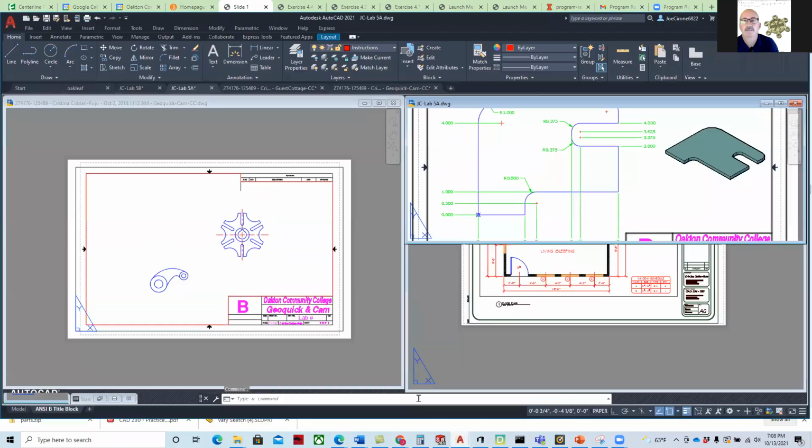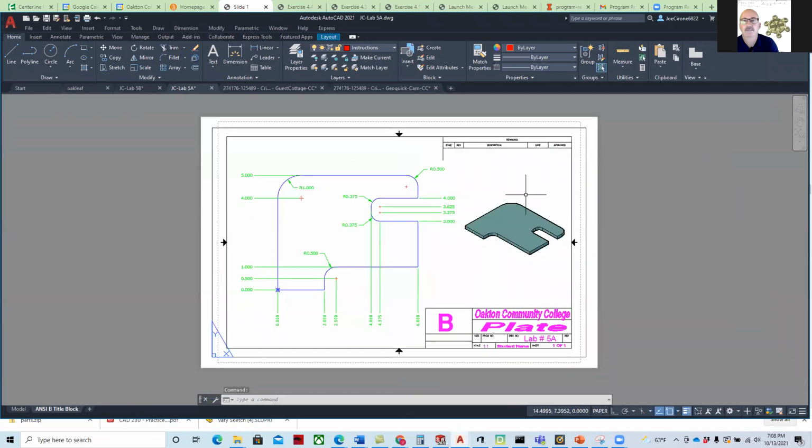So let's pull up last week's drawing right here. This is a great example where we have our origin or our XY axis at this point right here. And then the dimensions are ordinate dimensions in the X axis going this way and in the Y axis going this way. And then we can get those positions with absolute coordinates. So for example, if we wanted to locate this circular radius, we would locate that at X 2.5, Y 0.5. If you're running a CNC machine, numbers like that work really well because most of those machines are programmed off of a G90 or an absolute coordinate system.